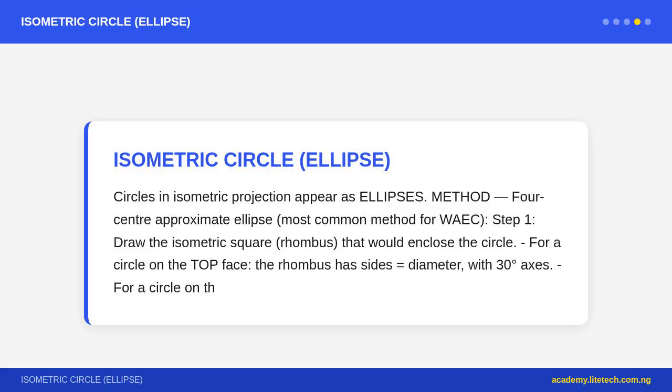Question 2. Describe how an isometric box of dimensions 60 mm x 40 mm x 30 mm, L times W times H, would be drawn. Answer. 1. Mark the origin point at the front bottom corner. 2. Draw the right axis at 30 degrees right, length 60 mm. 3. Draw the left axis at 30 degrees left, length 40 mm. 4. Draw the vertical axis straight up, 30 mm.